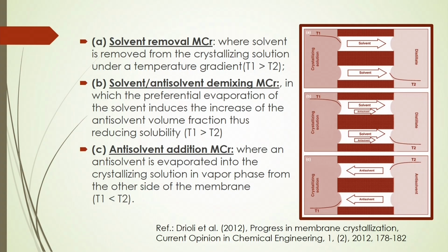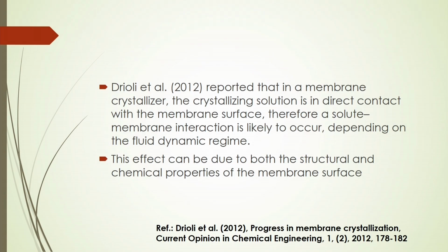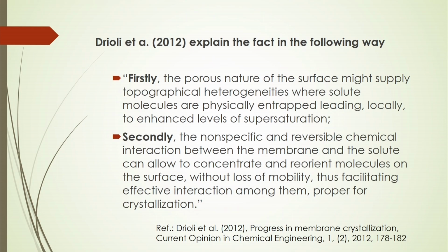So, according to Dewey et al., in the membrane crystallizer the crystallizing solution is in direct contact with the membrane surface. Therefore, a solute membrane interaction is likely to occur that depends on the fluid dynamic regime. And also the effect can be due to both the structural and chemical properties of the membrane surface.